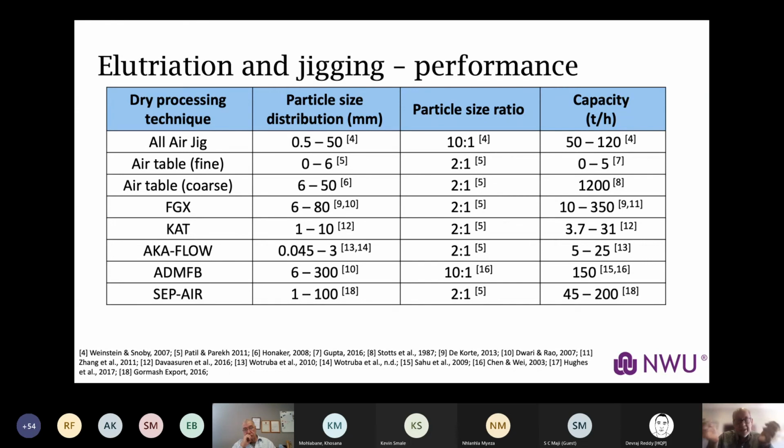And if you look at settling theory, it's very clear that the relationship determining how fast the terminal settling velocity of a particle in a fluid, whether it be air or water, is linearly related to the density. In other words, if I double the density of a particle, I will double the settling velocity, but it is a power cube, to the power 3, in other words, cubed to the size.